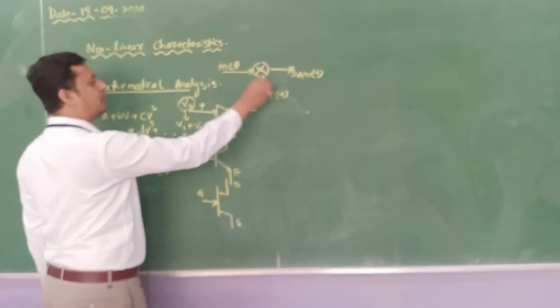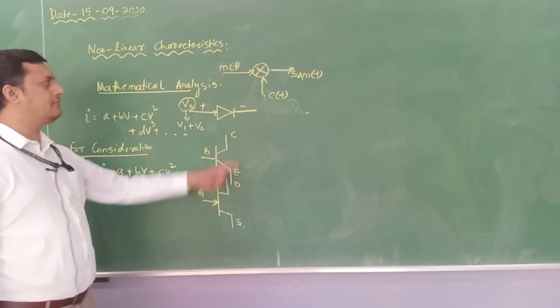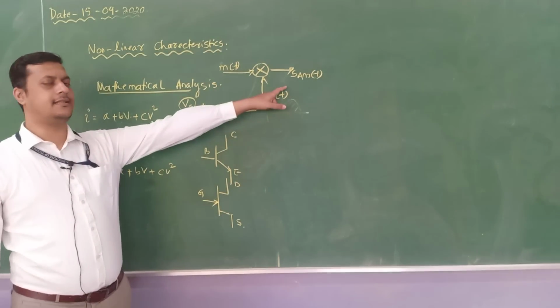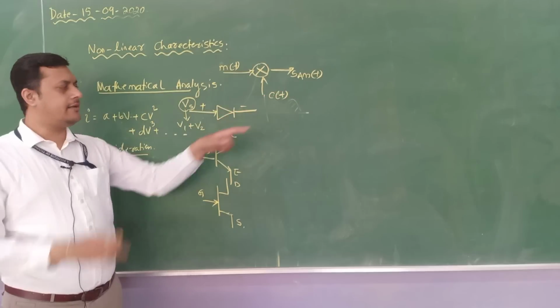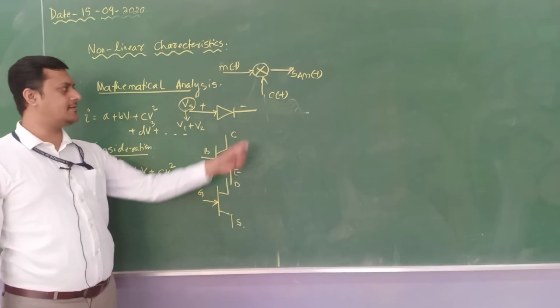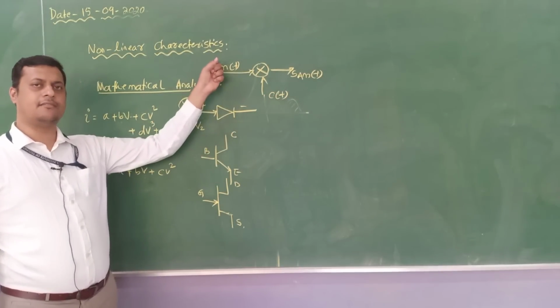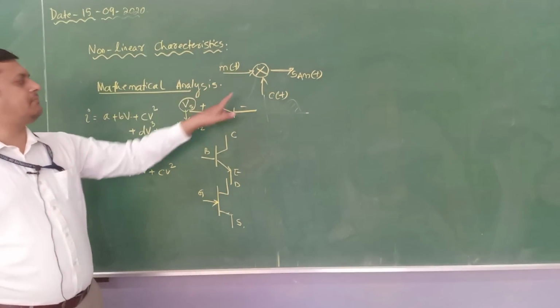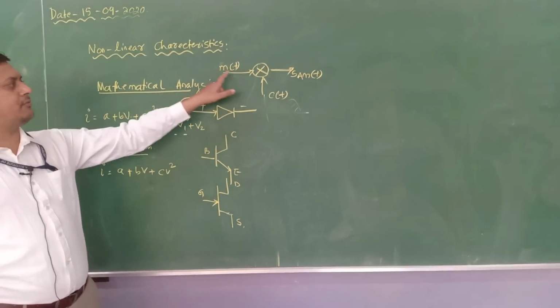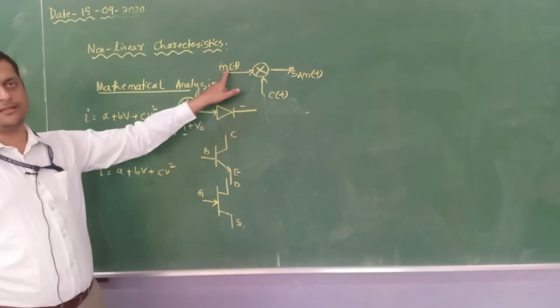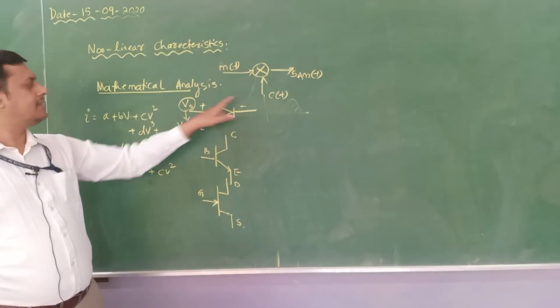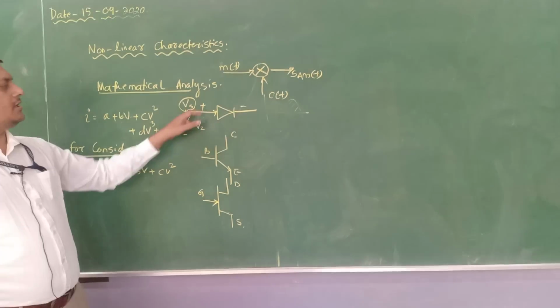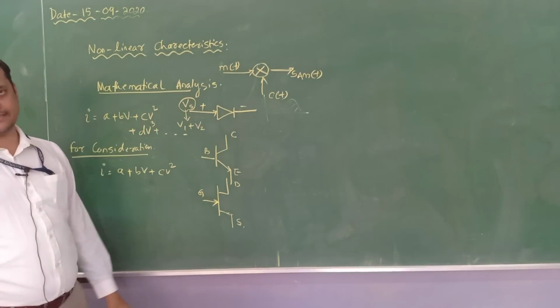So that means two potentials are provided to a device through which the AM signal is generated, with some change of characteristics of the carrier with respect to the message component. Let us consider this mixer is replaced by a diode. So how many potentials are we providing? Two potentials. One is message, one is carrier. So V1 plus V2. So the supply potential is this.